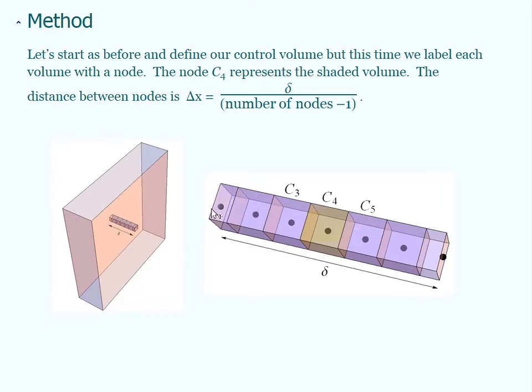Okay, and so this would be a row through Excel, and each of these would have values corresponding to the concentration that's in this one region. And that region would represent the volume here of our control volume. So what we're going to do is a mass balance again, just like we did before, but now we're going to do it on this volume, and our volume is now going to be finite, and so we're not going to be deriving the differential equation anymore, but we're going to be just simply doing a mass balance for this little volume element. And so what we can do is break up our solid.